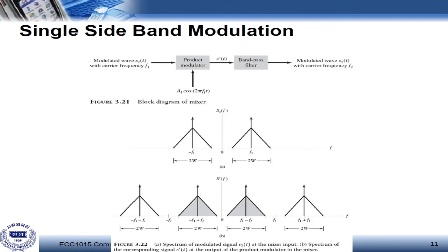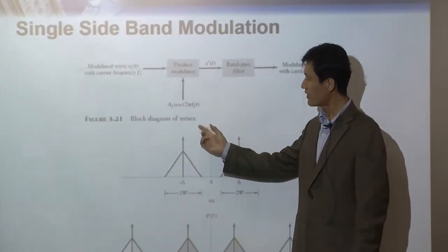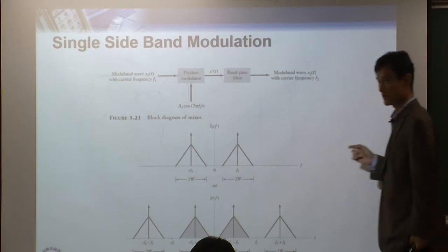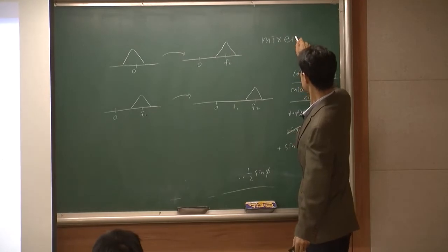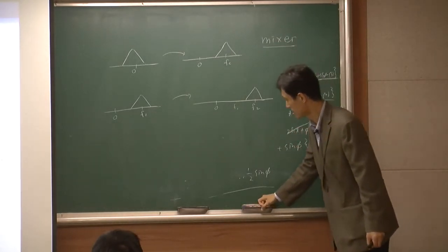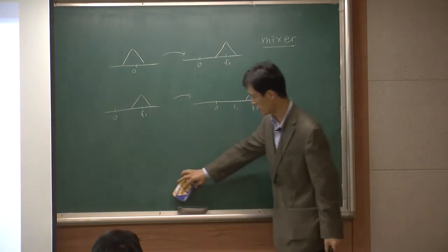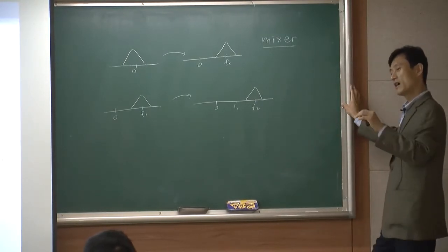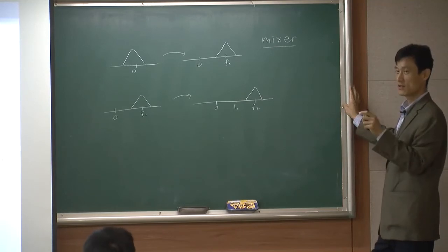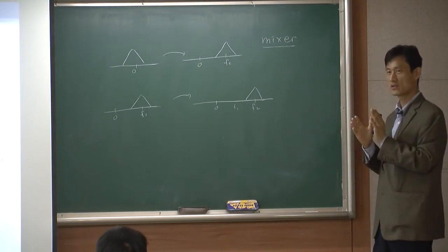When you do frequency translation, how to do that is in hardware, we have a hardware called a mixer. Maybe you want to remember something like this. Mixer. Later, when you work in your job, some of you probably hear mixer a lot of times. Every time people in the company say mixer in industry, that means you are translating the frequency. You are changing the frequency.